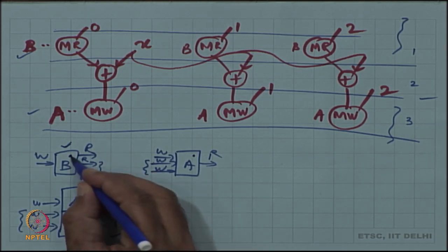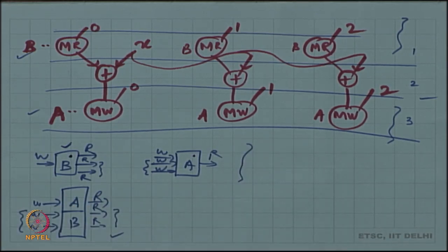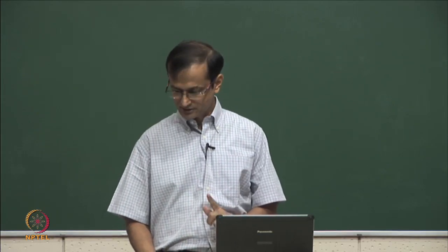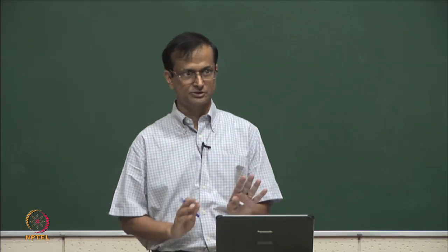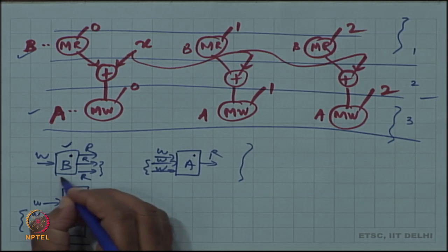In what ways? So, in this solution every cell has 4 ports. Here every cell has 6 ports. So, from just the cell area point of view, this one is more expensive. But this is not all, like we had said, there are other components that we also have to argue in terms of. There is this sense amplifier here.